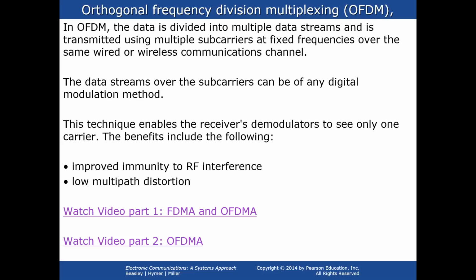Thus, in a 20 MHz channel, all the 1,200 resource elements carrying 1,200 symbols over 1,200 subcarriers are modulated with the appropriate modulation scheme. Now, since the data is modulated over 1,200 subcarriers, a transmitter will require 1,200 oscillators for its generation, and another 1,200 will be required by the receiver for proper demodulation. The hardware complexity and sheer amount of power consumption would have left OFDM a theoretical idea, far from implementation.